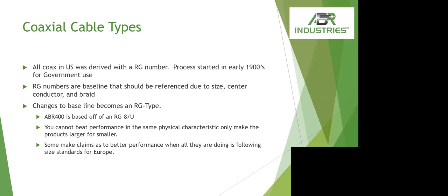When you look at the products that are out there today, you want to look at testing at a couple key frequencies: 30 megahertz, 50 megahertz, 150, 220, 450, and then up to 1.2 gig. Those are standard tested frequencies that are used in the market. It's a baseline that all manufacturers follow. We go much higher than the frequencies I just listed, but it's very important to realize, because when somebody says that it's a little bit better at 144 megahertz, well, technically, yes, all coax gets better at 144 versus 150. And depending on how some people round numbers, you've got to be careful. So what I'm trying to say is always be conscious of what you're looking at.